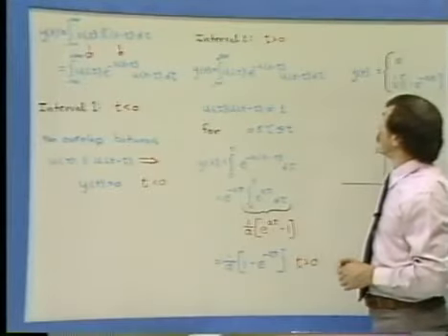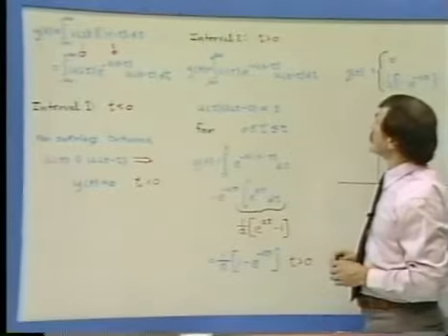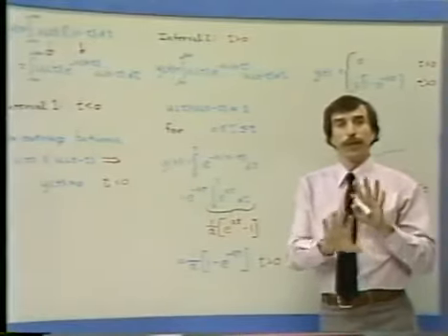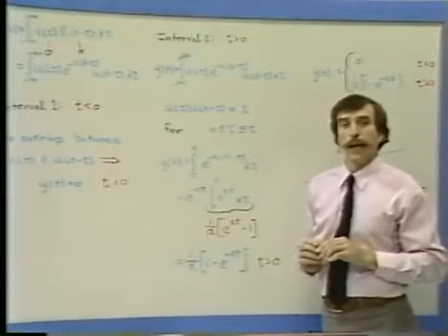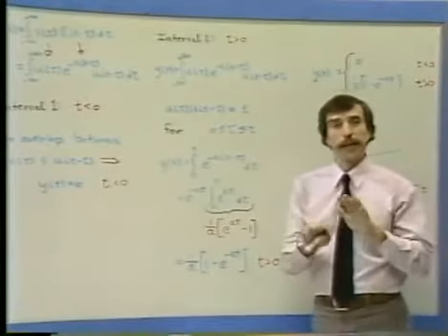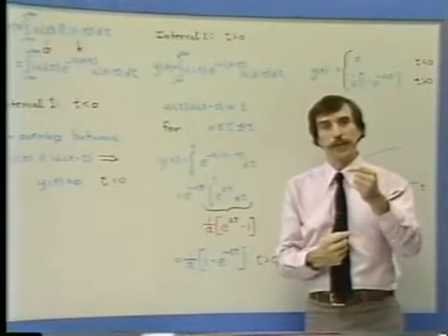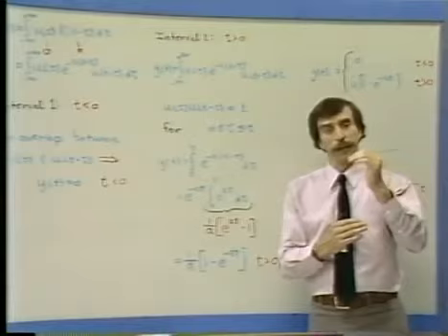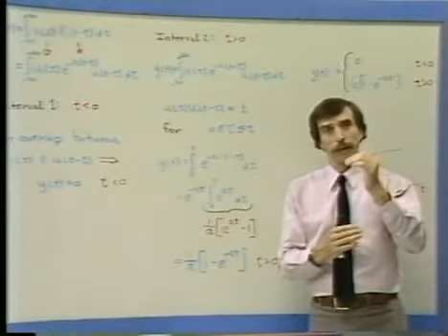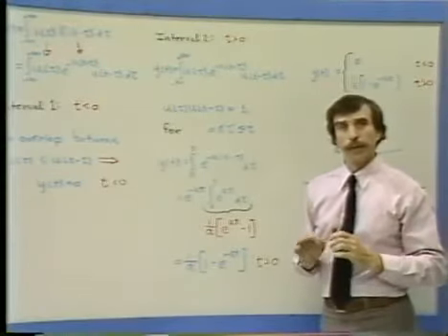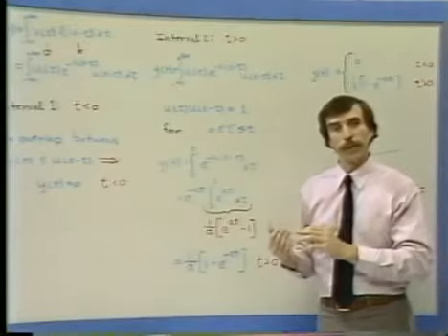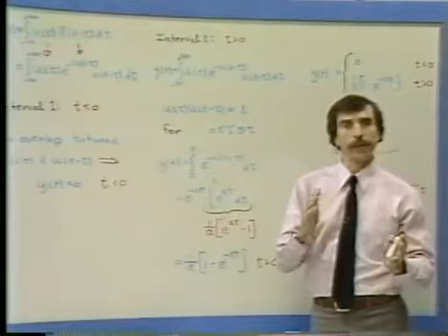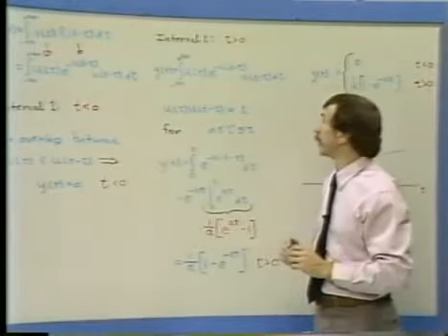Okay, now we can likewise look at the interval where the two unit steps do overlap. In that case, the overlap of the unit steps gives us a range on the integration. In particular, the two steps overlap when t is greater than 0, from tau equals 0 to tau equals t.